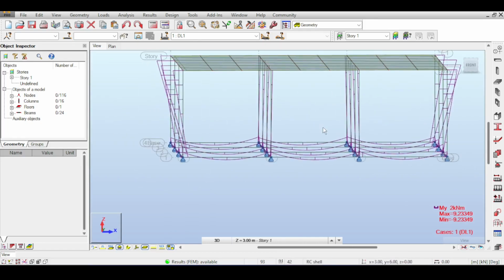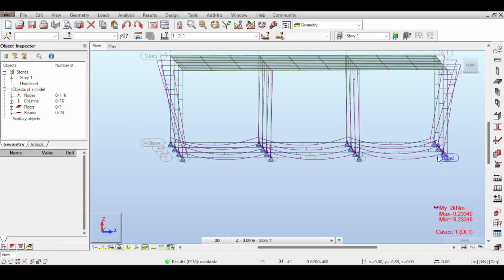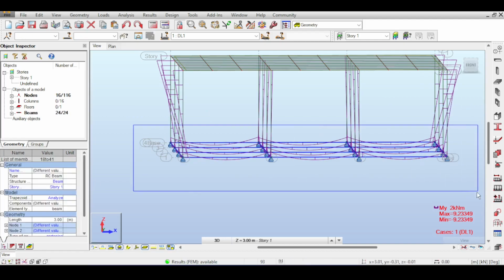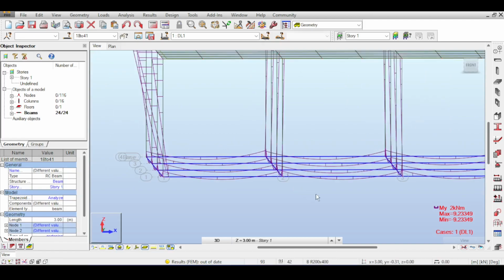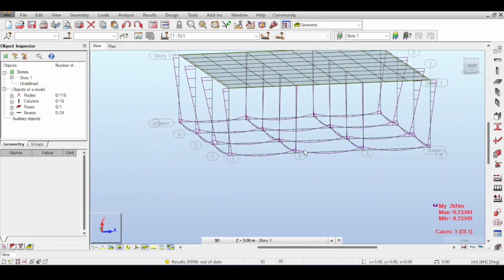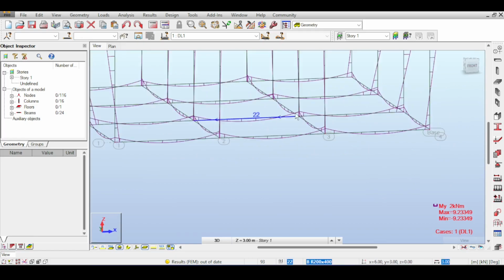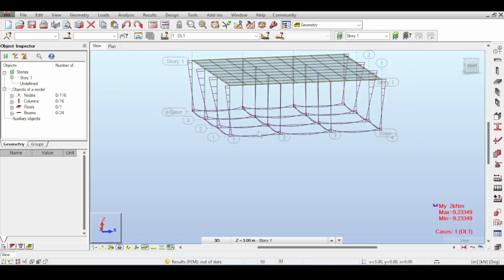Of course, this is incorrect because it's either this or that. You cannot have supports and have elastic foundation. It's either you have elastic foundation that carries the structure or you have supports that carry the structure. You cannot have both. So let's remove the supports. Now I'm still predicting instability because the supports are in UZ and there is nothing in UY or UX. Now, truth be told, our structure should not be unstable because there is friction. This is some of the tests you would do on a structure.